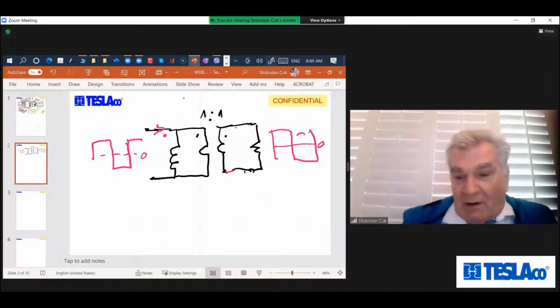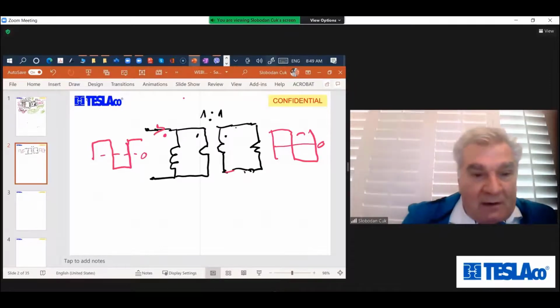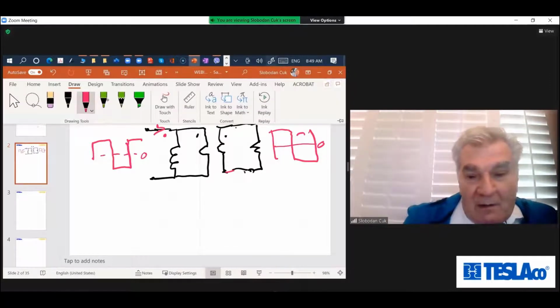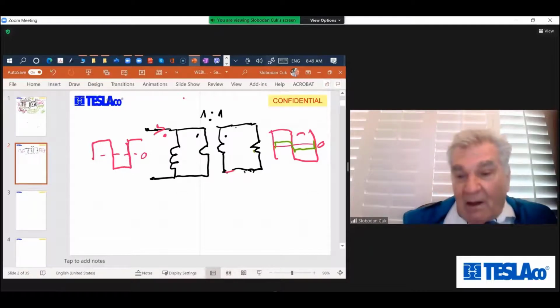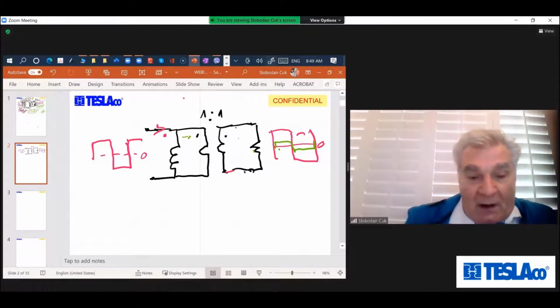Now, if you have a resistor, whatever value it is, it'll create square wave voltage here, it will create the square wave current here, right? That square wave current here will reflect as the square wave current here, and therefore there will be square wave current on this side, like here, and so you have square wave voltage here and square wave current.